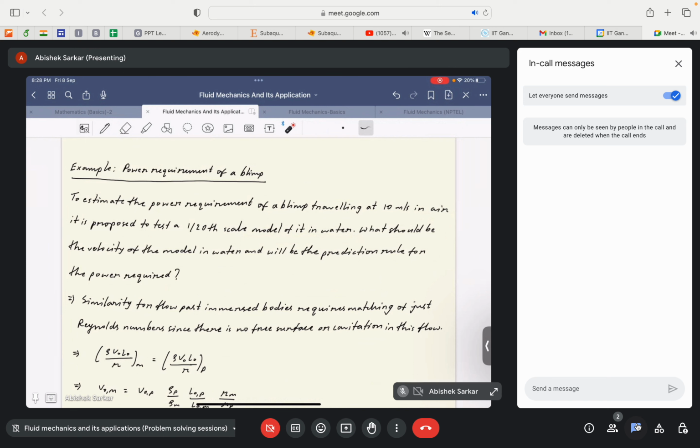Okay, so this discrepancy is being handled by using a different fluid of different density, ideally water, that helps in conducting experiments that has high discrepancy in the length scales. This discrepancy in the length scale would have eventually resulted in discrepancy in the velocity scales. So this discrepancy in the velocity scale is smeared out or cancelled out by using a high density fluid, that in this case is water.